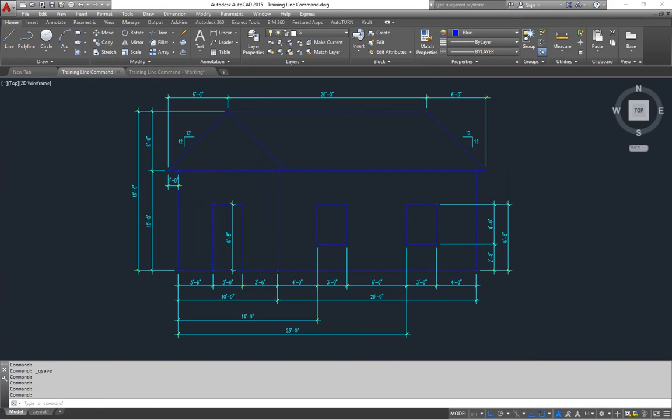Okay, now let's draw one of these openings, assuming they're like windows or something. As you can see, they're 3 feet wide and they are 4 feet tall. Now they are going to line up with the door opening, so this is going to be at 6'8" at the top of it. So let's just use absolute coordinates and start at this top corner of this window